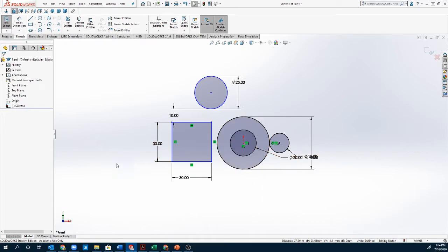So let's take a look, for example, now at the icons that we're seeing. So we have here this straight horizontal line that's telling me that those are horizontal to each other. If we come over here, we have our tangent. The one over here is our coincident point. What that's saying is that the center of the circle is at the origin. We have on our square, we have some verticals. So we have 2 lines that are vertical and we have 2 lines that are horizontal.